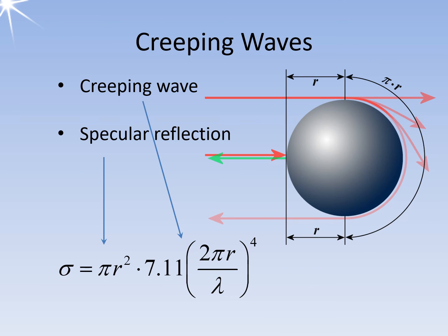So far, we have assumed that the reflecting surfaces are much larger than the wavelength of the radar transmitter. Artillery shells or simply raindrops can also be equal to or smaller than the wavelength. Two main effects occur here: specular reflection and the creeping wave. However, the addition is phase-dependent. A phase jump of 180 degrees occurs during specular reflection.